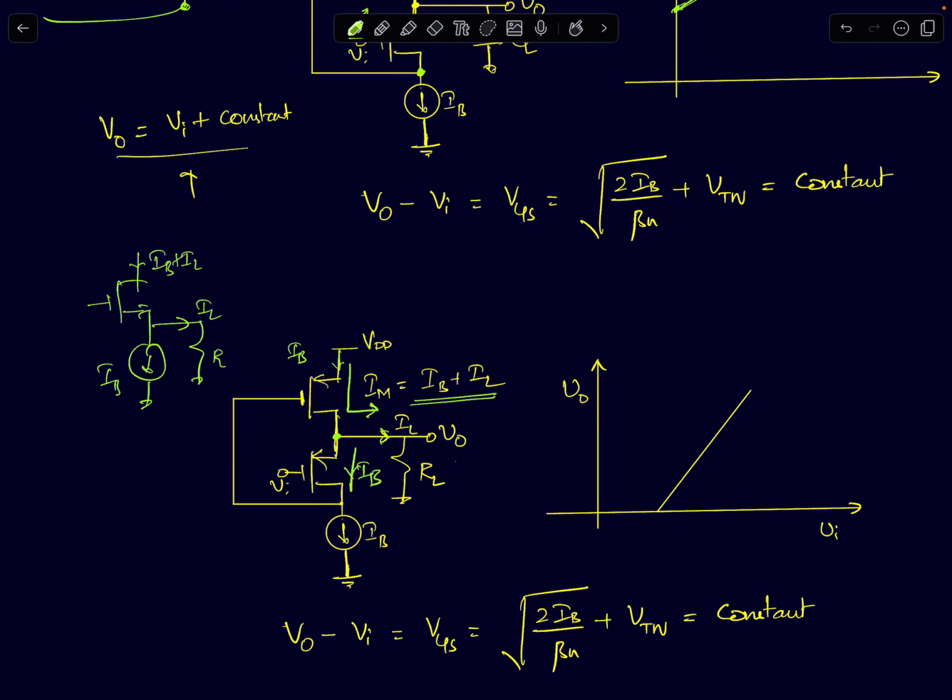Now you have a PMOS device, which is not even a source follower device, which is a common source device, which is carrying this current. Okay, and the VGS of this device is always constant. If we ignore channel length modulation and all of that right now, the entire load current has to come from the upper PMOS device.